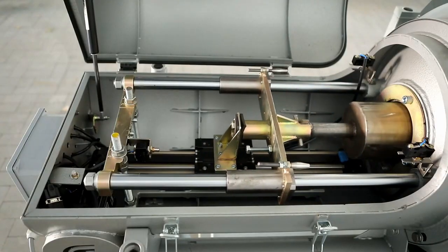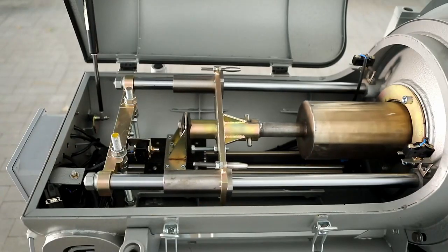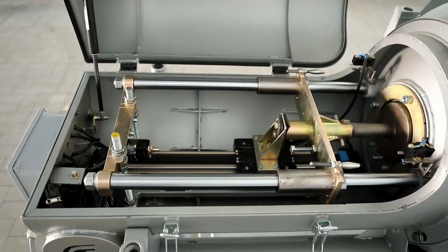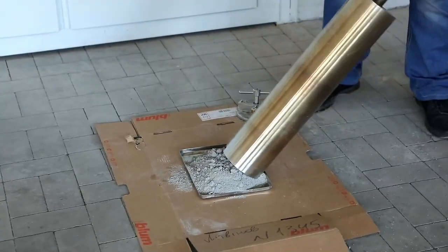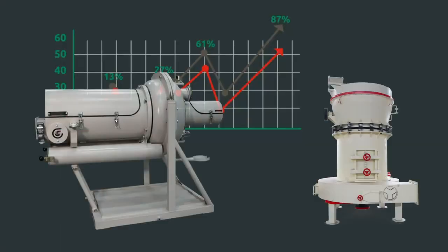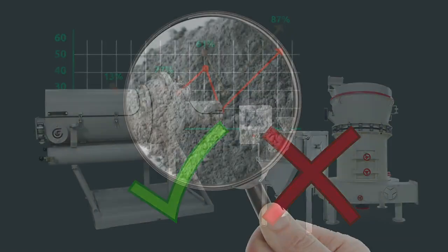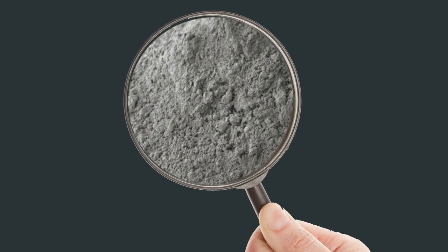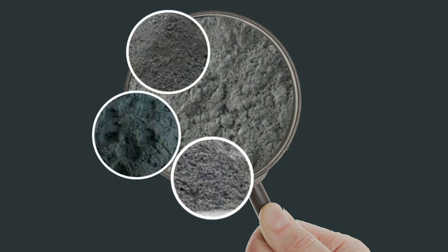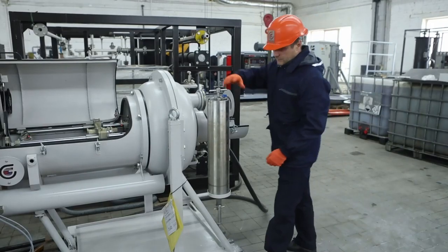In these machines, an additional factor of mixing the constituents is caused by motion of the operating chamber relative to the inductor. As a result of processing that takes just a few minutes, vortex layer machines ensure finer pulverization and better mixing compared to ball, hammer, and centrifugal mills, and can be used to pulverize and mix refractory materials, such as tungsten carbide, zirconium carbide, titanium boride, molybdenum silicide, titanium carbide, molybdenum boride, and others.